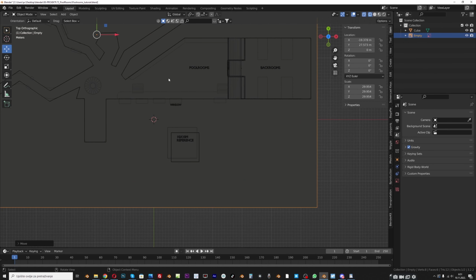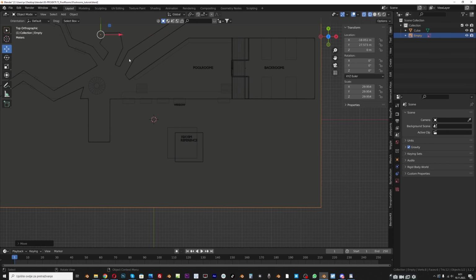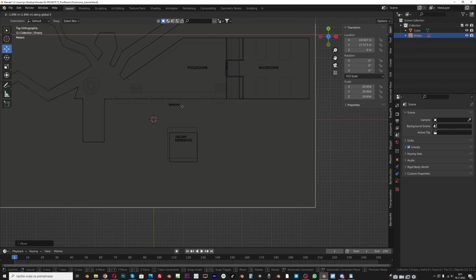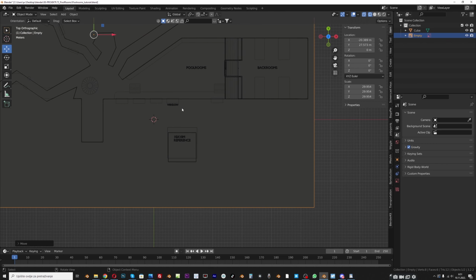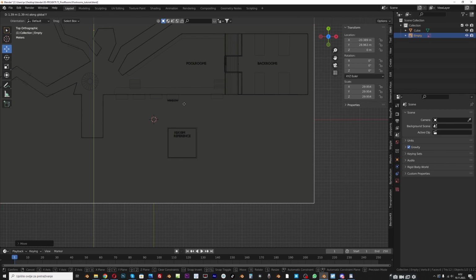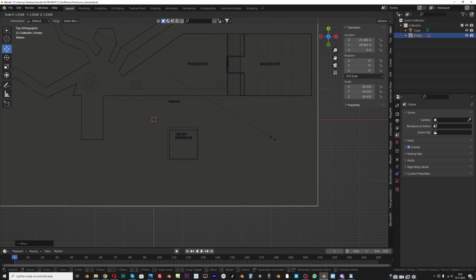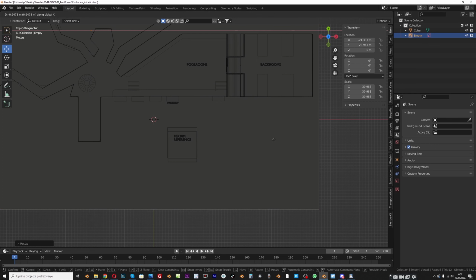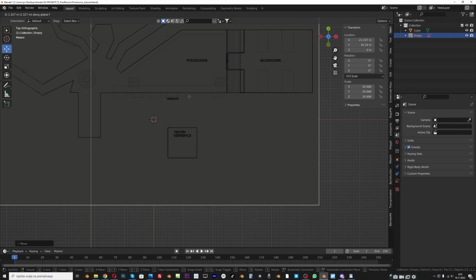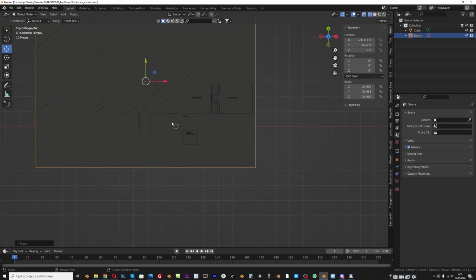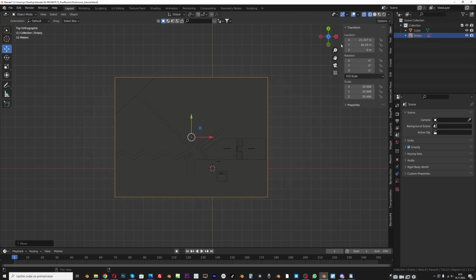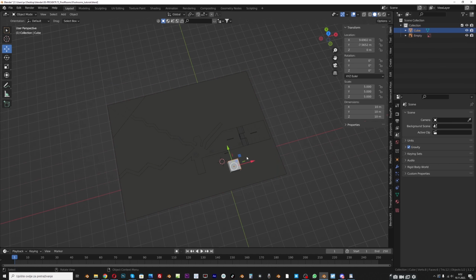So you can always use shortcuts. The shortcut for grab is G, and if you press X we can move this on X axis. So GX and now GY, and scale this a little more. Okay, this looks pretty good, and I can now go back to viewport display, and I will now delete this cube.